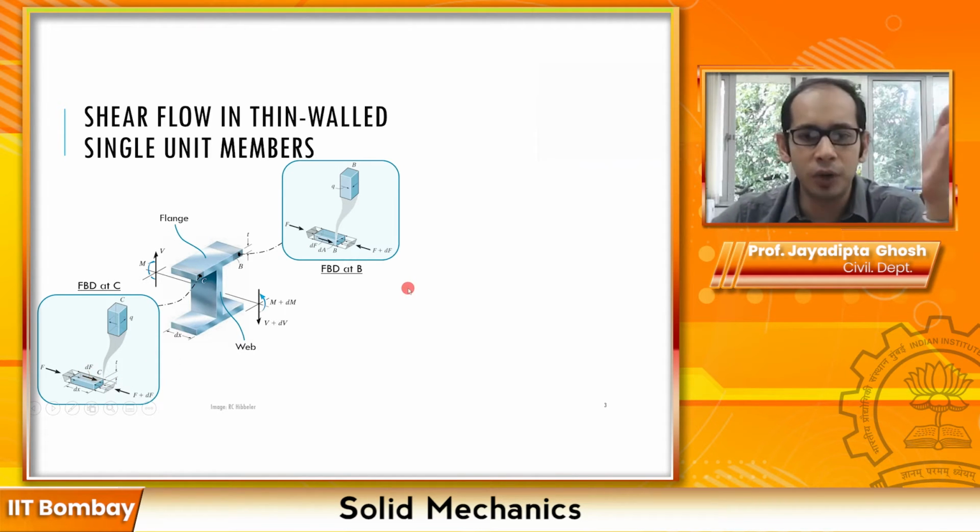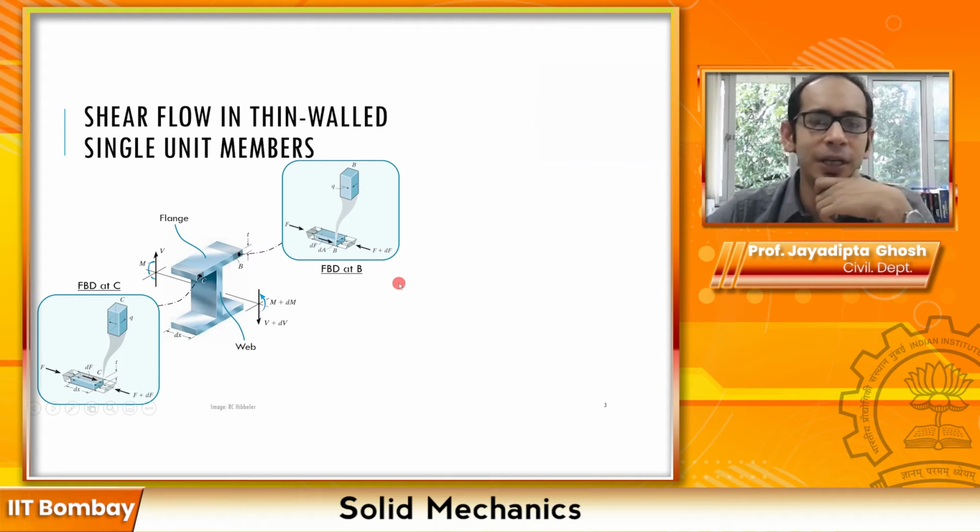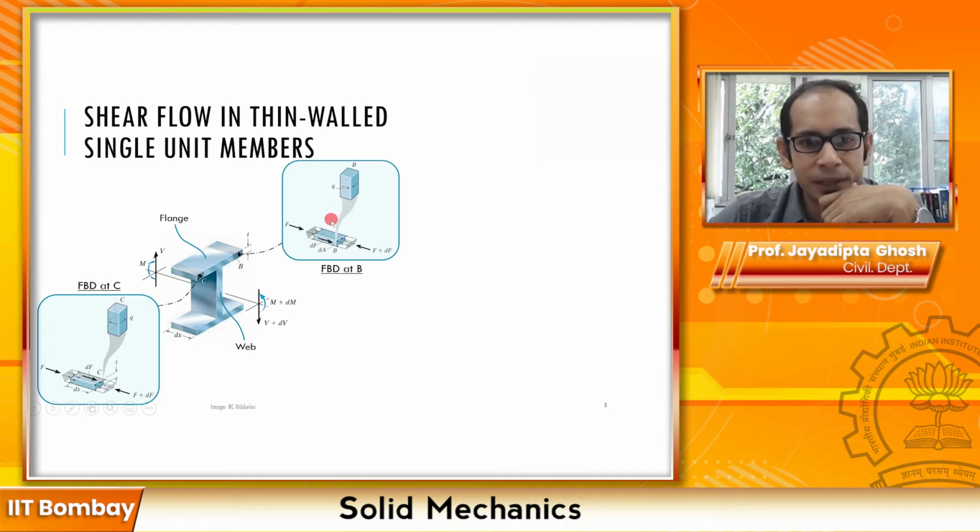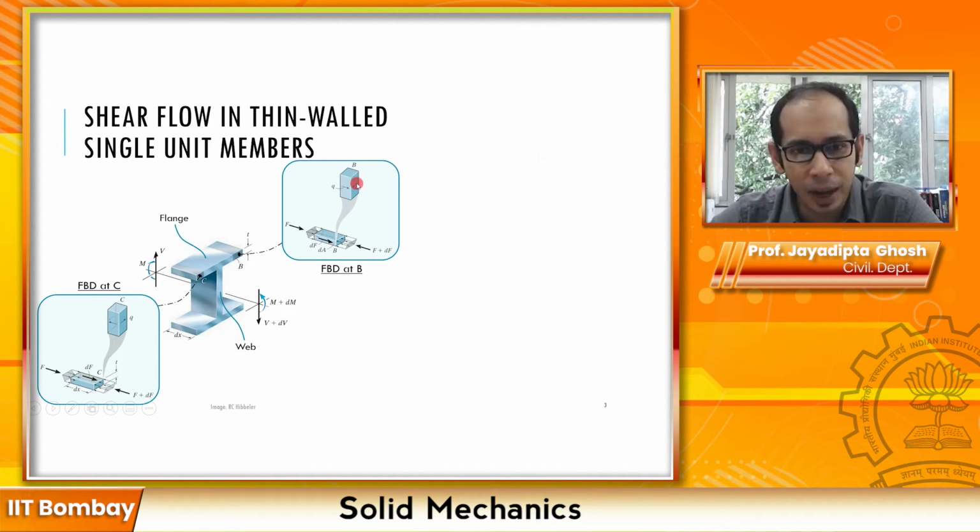Now what do we get out of this? And maybe you are already getting a hint of how the shear is going to act. So this is the force. Now if I go from the force to the shear flow, q over here, or the shear stress, q and tau are all related. If q or tau is acting over here, because of complementarity you will have a shear about this direction over here. Similarly here, if your dF is acting on this face, because of complementarity you will have a shear force, or a shear flow, or the tau, which is acting something like this.